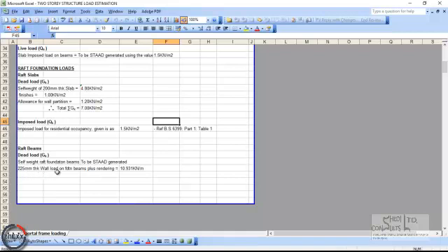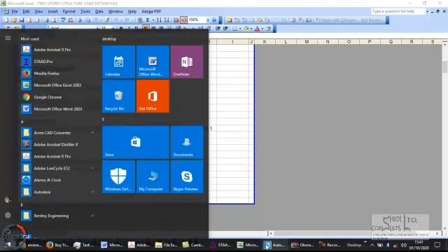The 225 mm thick wall load, inclusive of rendering, is taken as 10.91. This was calculated from the self weight of block work plus associated rendering on both sides. 13 mm rendering, self weight of block work is taken as 2.87 kilonewton per meter square, plus rendering is taken as 0.3 kilonewton per meter square. Add on both sides 0.6, that gives us 3.47, and the height of the block work is taken as 3.15.